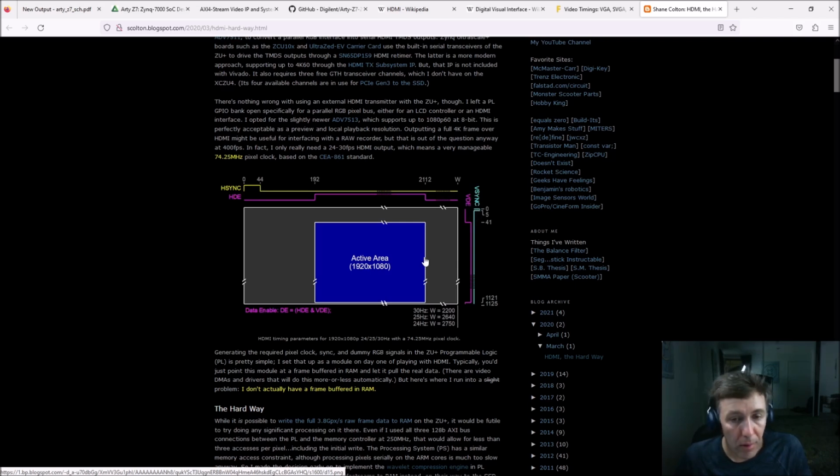So in total, what we really need for our video signal is vertical sync, horizontal sync, and data enable, which normally and usually is combined. Two signals are combined into one, data active, and the data bus to represent information about pixel colors.